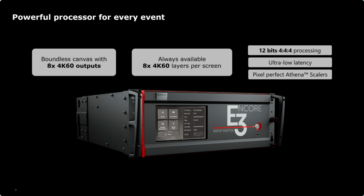So let's check out the processing scheme inside this extremely powerful processor. It is what we call Boundless Canvas, with 8 4K60 worth of screen resources, and of course, 8 4K60 layers per screen resource, or an alternative way to look at it is 4 4K60 mix layers. And as always, we do everything 12-bit 444 processing internally with ultra low latency on our pixel perfect Athena scalers.